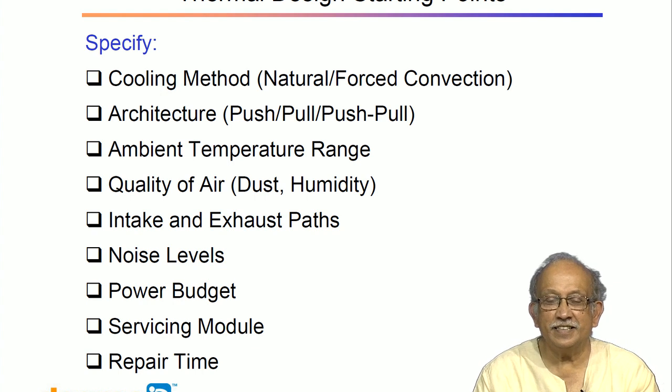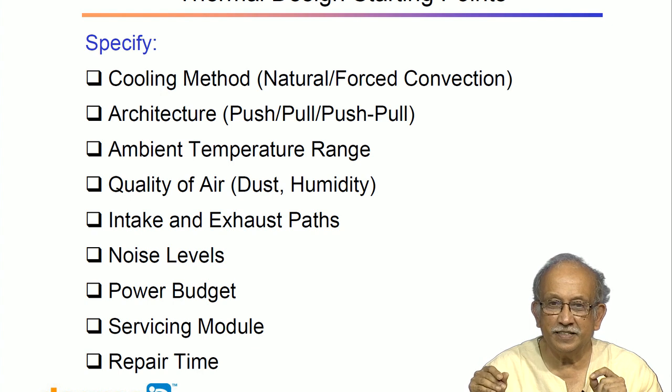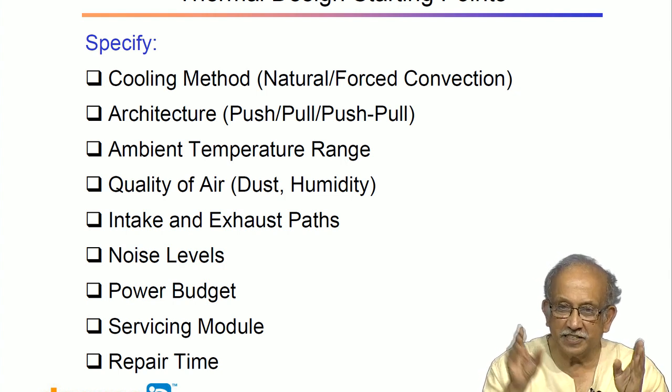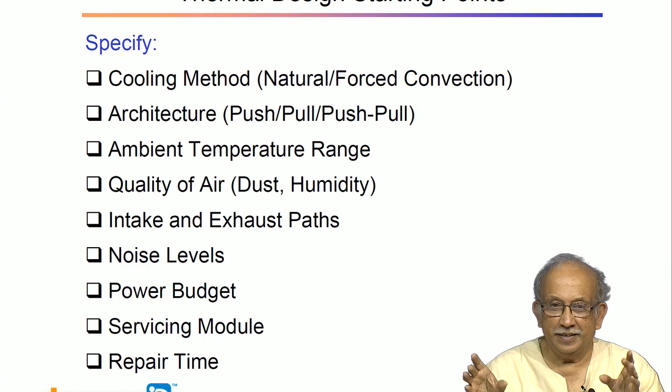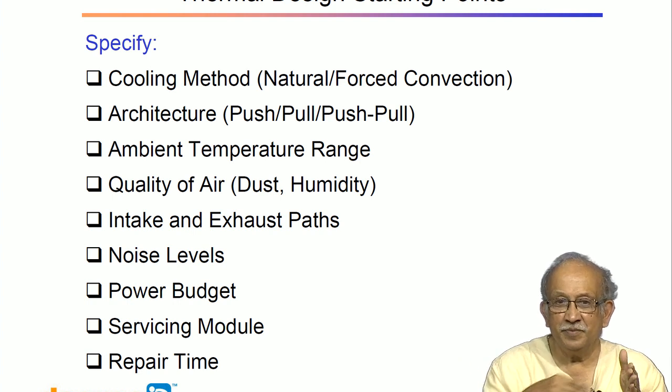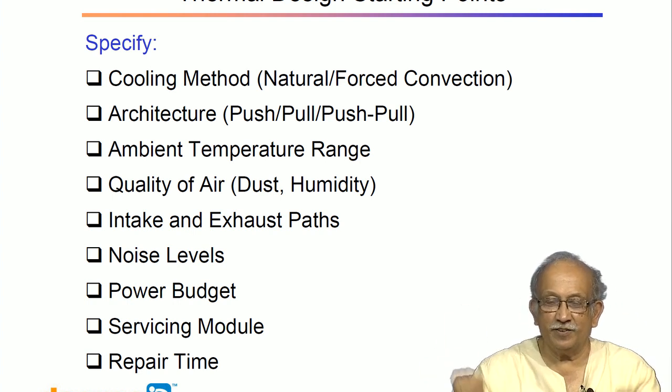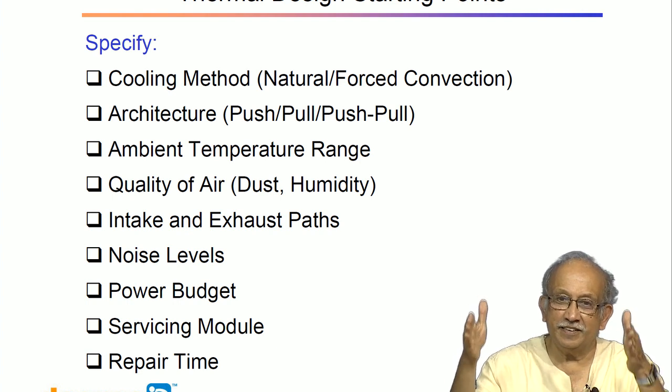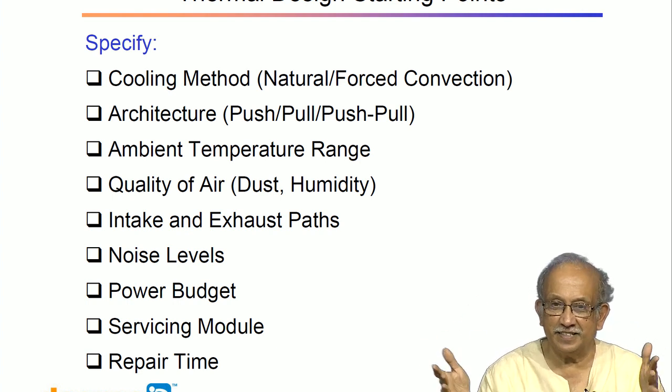water will start condensing on the sides of the refrigerator, and if you take the old type of mineral wool insulation, soon the insulation gets waterlogged. Even in spite of your having the best polyurethane formed in place insulation, still condensation is real. So, they have found out a much easier way. They run the condenser coils inside, which has a double benefit. You have much more area for the heat to spread, and it also aids in anti condensation.